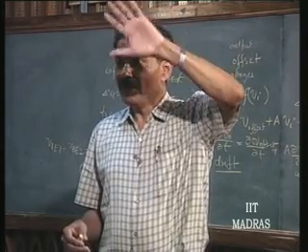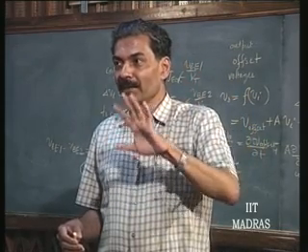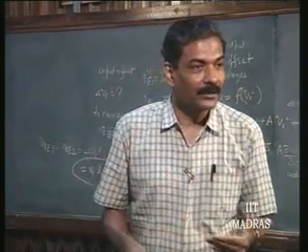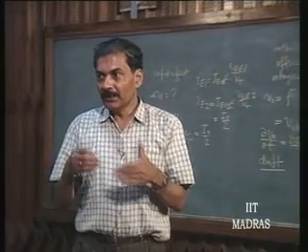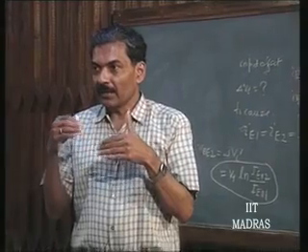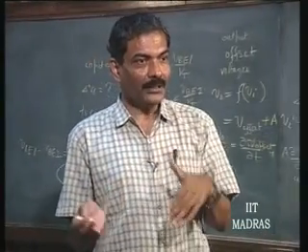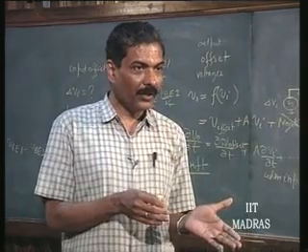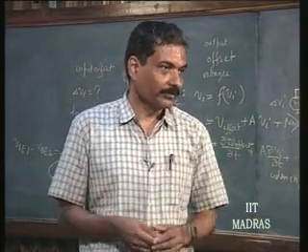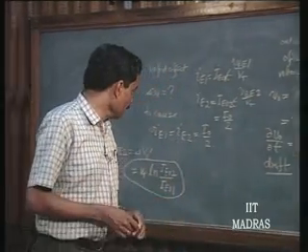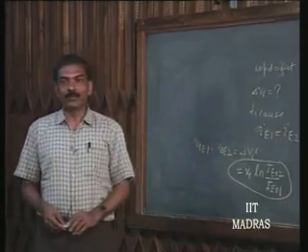So always remember that if you are concerned about input impedance, you have to sacrifice input offset. This is the primary idea behind selecting the input stage. If you want low input offset, go for low input impedance, that is all. You cannot help it. So delta VBE means this is what is called input offset.